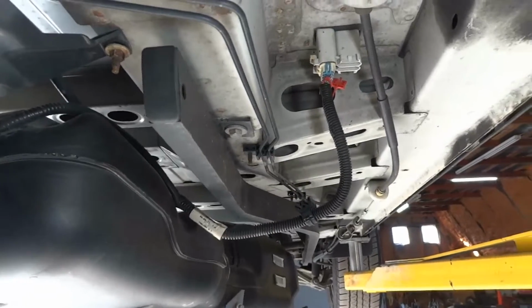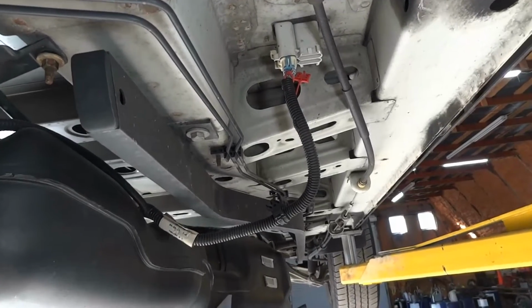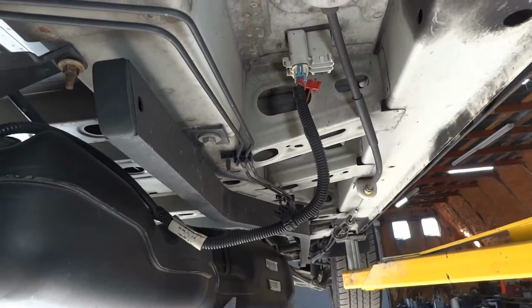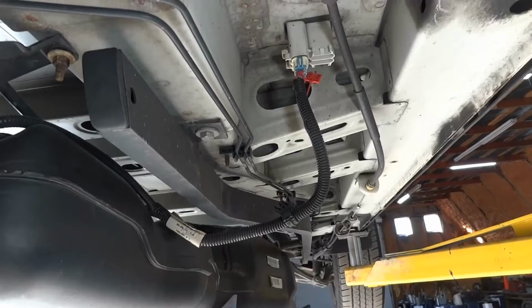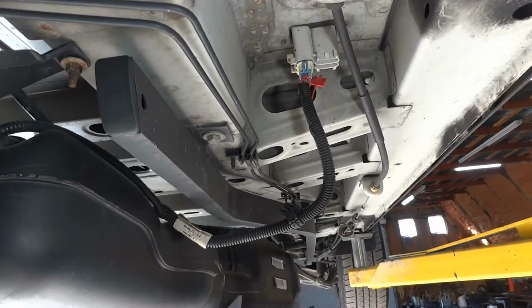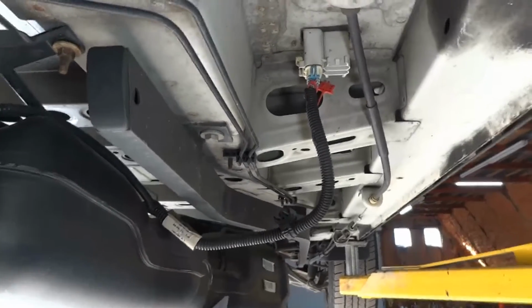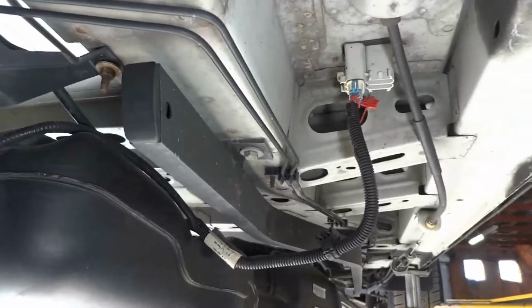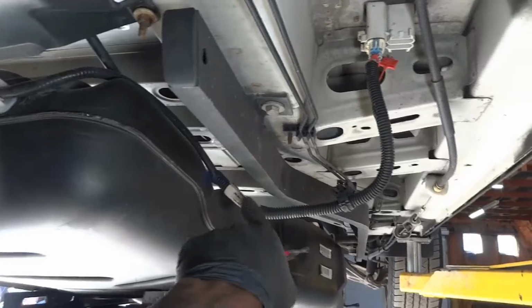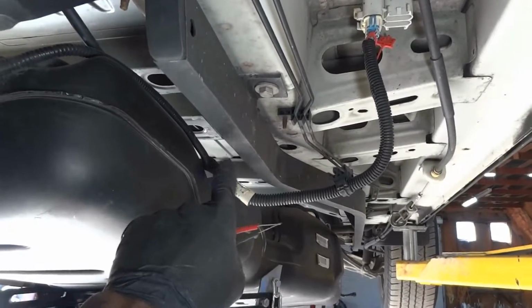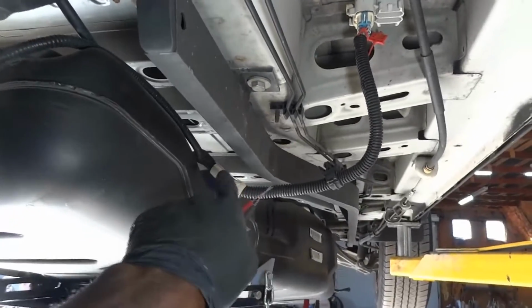So after checking the resistance of the old solenoid and the new one, there isn't a big difference between both of them. The new one is reading about 20.6 ohms, and the old one is reading 20.8 ohms. So that tells me that our problem is most likely not the solenoid. So we could have an open in the wiring harness between this connector over here and the solenoid itself. So the wiring on top of the tank could be the problem. So we have to test that first and make sure that the wiring is good before we replace that solenoid.